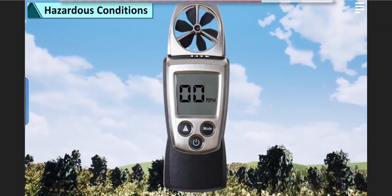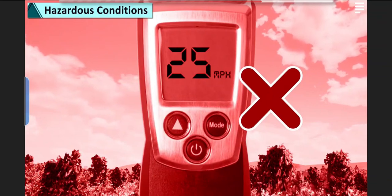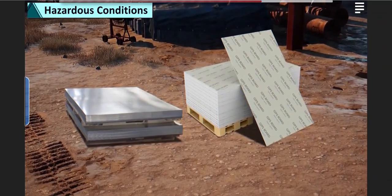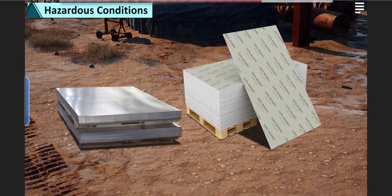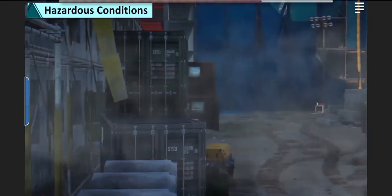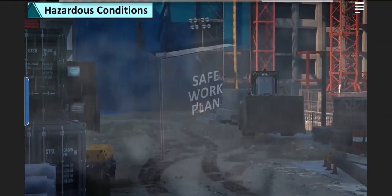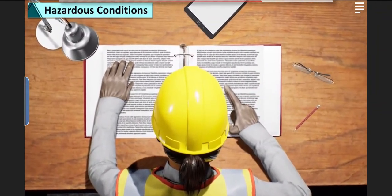Never operate any MEWP in winds above 25 miles per hour or above the manufacturer's recommended wind speed limit, whichever is lower. In even light winds, take special care when handling materials that can act as sails, such as panels and metal sheets. Other weather conditions such as fog or rain need to be accounted for in the Safe Work Plan, and the plan must be reassessed if weather conditions worsen.